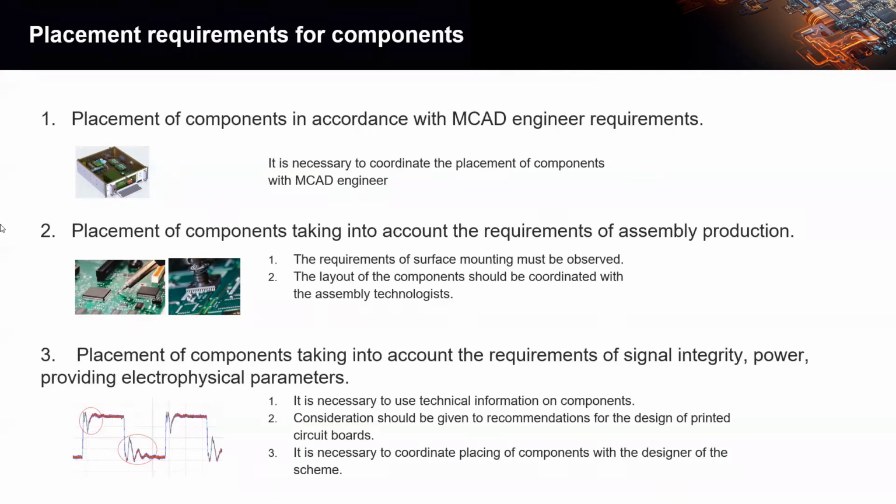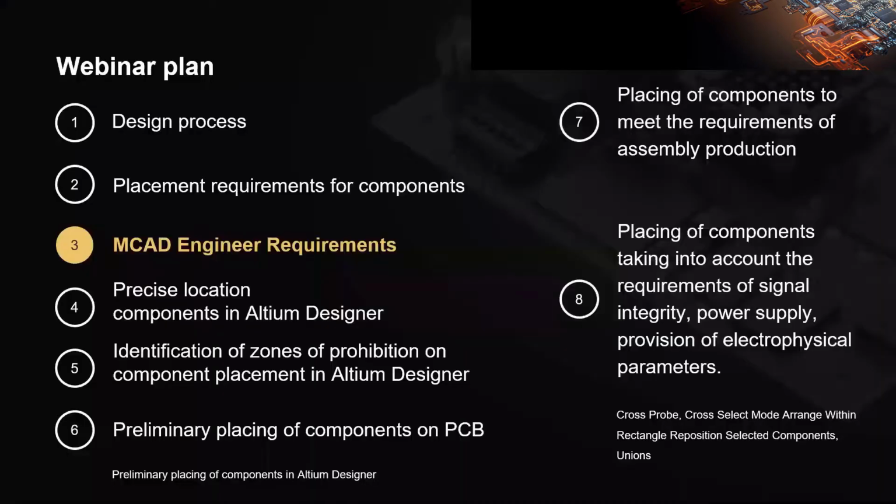A couple other things have to be considered as well when you're placing these components. You've got to take into consideration all of the other components around them. Also, whether the board is going to have a rigid flex. Is there a flexible section of the PCB where the footprints may interfere with each other depending on their height? Okay, so we've also got some other placement considerations for signal integrity to avoid overshoot and undershoot and ring time, like shown in this O-scope of this signal down here at the bottom, right? So we've got a lot of these considerations that we have to take into consideration, right?